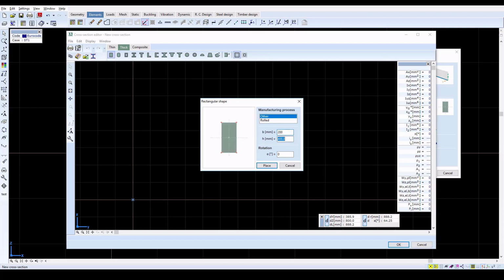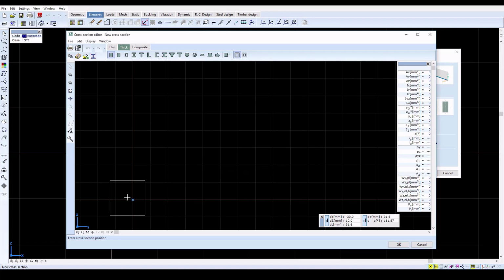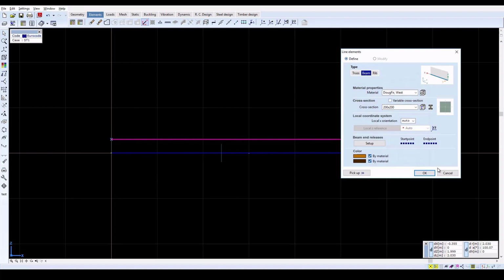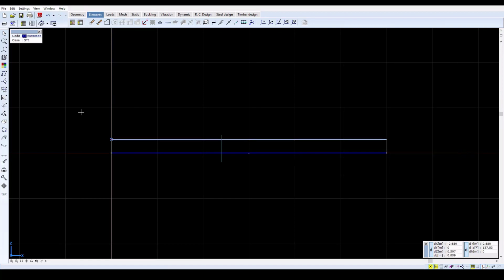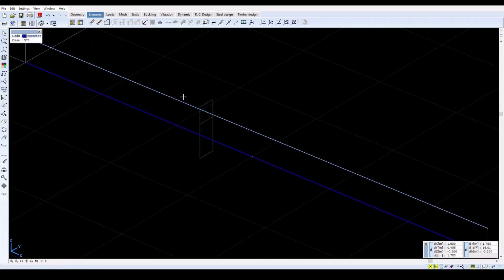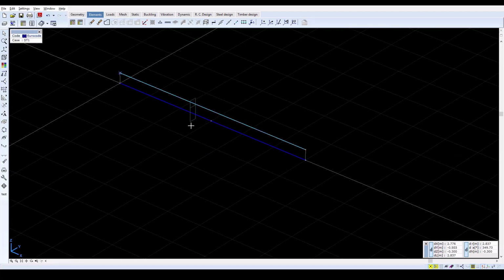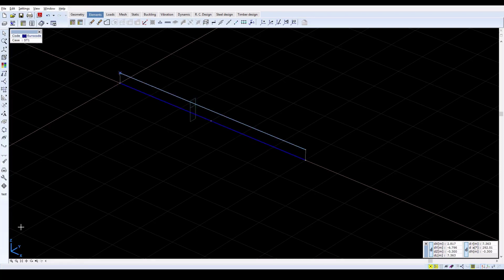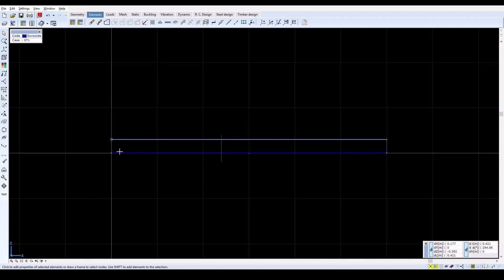The line-to-line link elements modeling the interface have 6 stiffness components. In this example, the local system of the line-to-line links is parallel to the global coordinate system. The interface is located at a ratio of 2/3 with respect to the master nodes at the bottom. In this case, the horizontal slip stiffness, Kx, is provided by the line-to-line link elements, uniformly distributed over the length, and its value is usually based on experimental investigations, being slip tests.